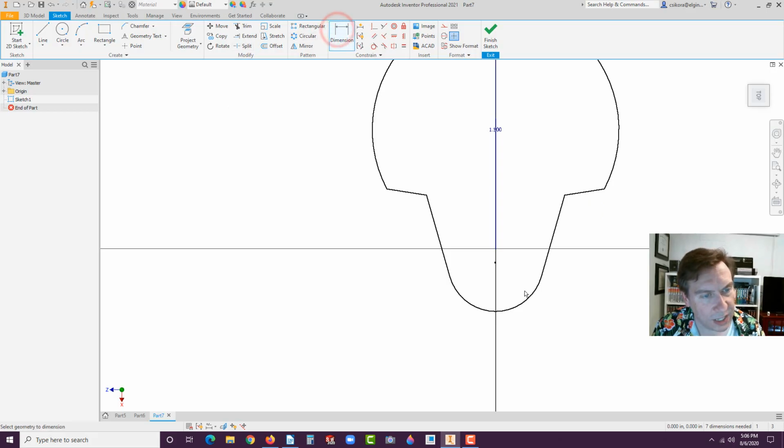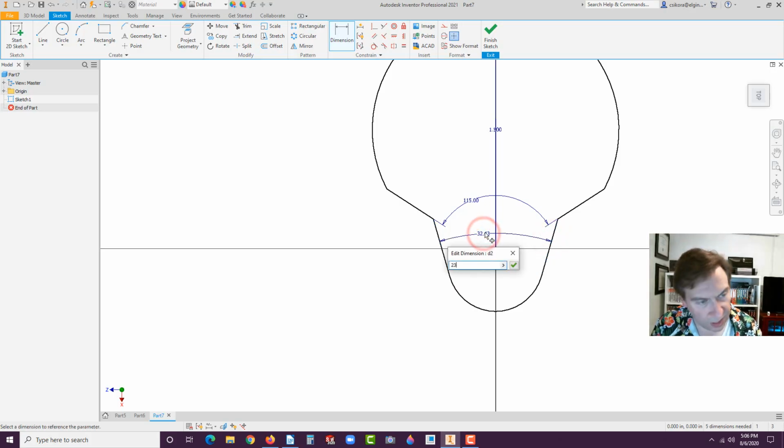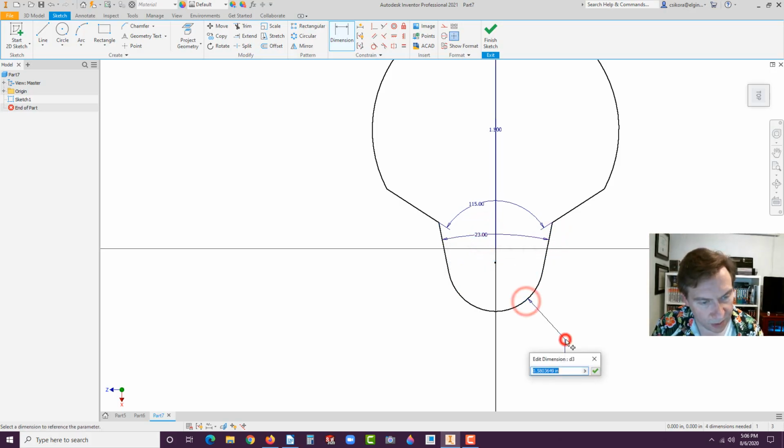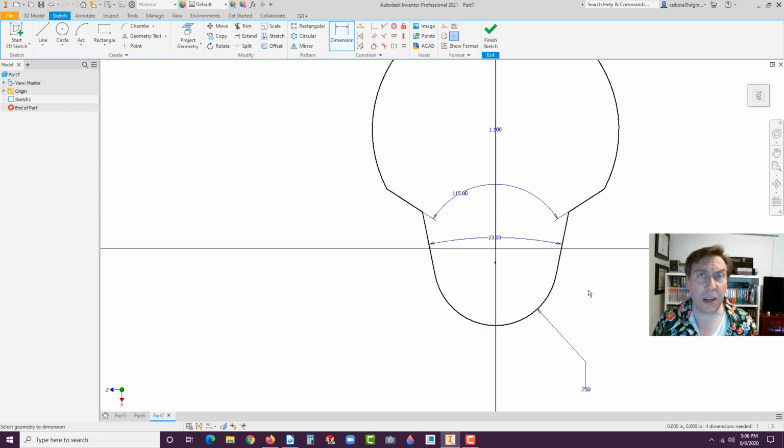Let's go to Dimension. Now, let's dimension from here to here, and this is going to be 115. And then from here to here, that's going to be 23. And then this bottom arc is 0.75. Okay. Now mine's updating pretty well.